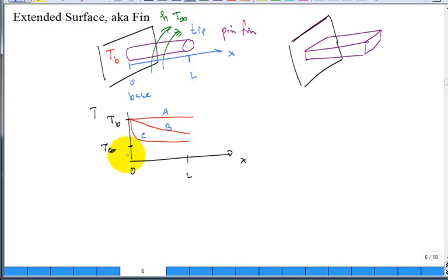It looks like half of the fin, if not more, is at the fluid temperature. Is it transferring any more heat in that second half of the fin for KC? No, it's not. So for KC we would think, well, it's easy to move the heat off of it into the fluid and hard to move it down the length. So probably the thermal conductivity of the rod is low for KC.